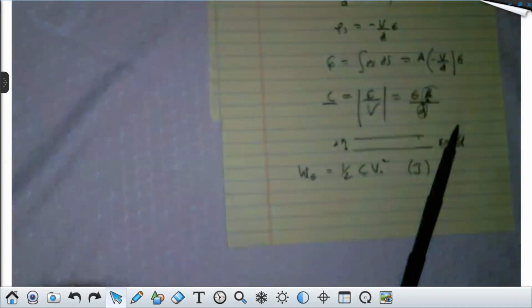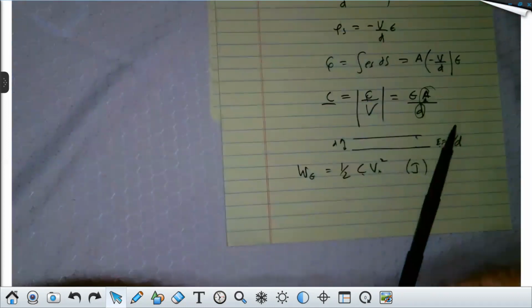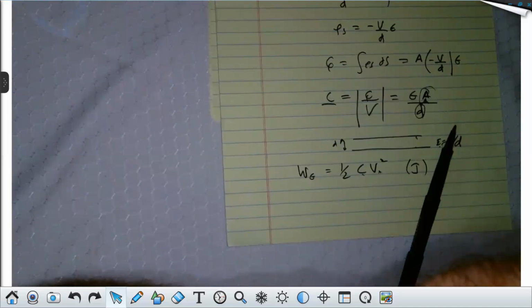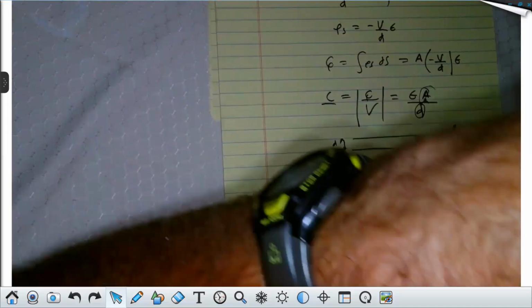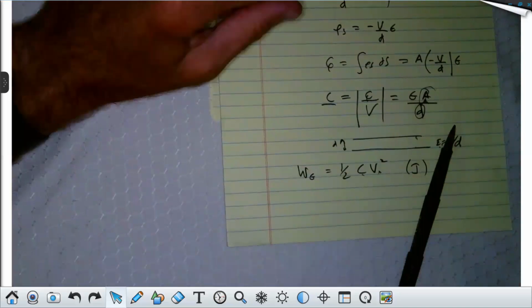When you get capacitances that you worked with in the lab, they're usually between picofarad and microfarad, right? Maybe 10, 15 microfarad. And they have voltages that they can withstand of a couple hundred volts. Our capacitors could withstand 10,000 volts, and they were 32 millifarad. If you do the calculation, we had 4 of them used in parallel to discharge it. The amount of joules we're using is, I'm sorry, tens of thousands of joules, and I believe that's right.